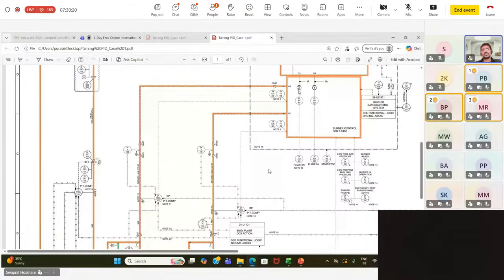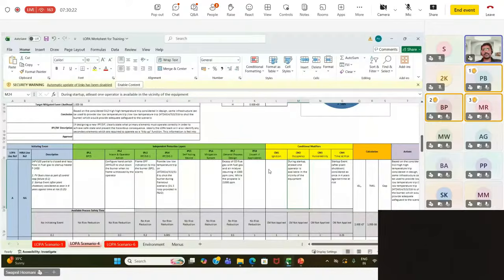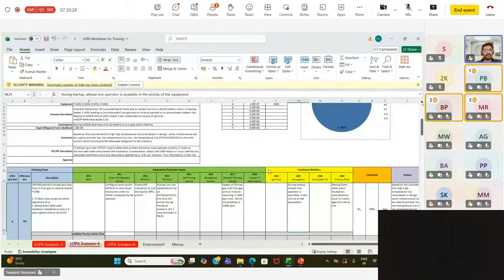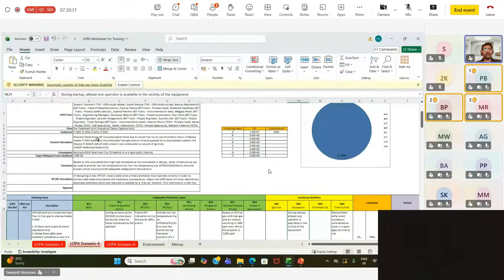Okay. So in this case, what is the worst that can happen if there is FV or this valve is partially or stuck closed? In this case, there could be possible flame blow off. The reason for flame blow off here is because of unsustainable flame due to lesser fuel to air stoichiometric ratio. So you guys would have done stoichiometry in your college days, okay?